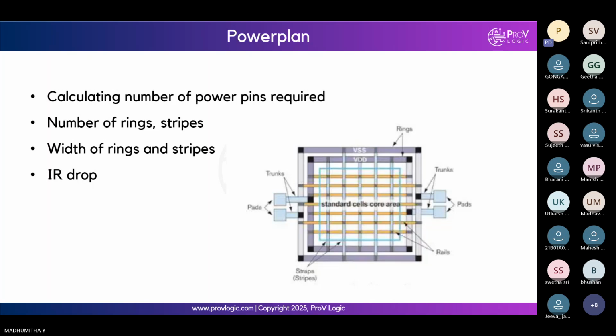See, the metal layer width will increase as we go from the lowest metal layer to the highest metal layer. So it is not necessarily wider. To give you a simple example, assume we have 9 metal layers in our design; the width of the metal layers will keep increasing as we go from M1 to M9.